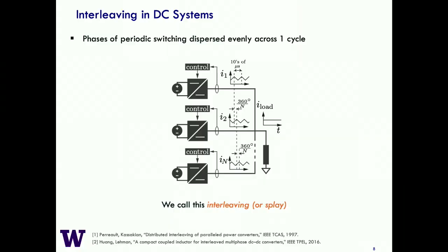And due to just Kirchhoff's current law, when all those currents sum up, those ripple distorted components that you don't want can just cancel out. So that's a really nice, elegant approach for canceling out this distortion without resorting to large, bulky filtering elements. You just let KCL do the work for you.